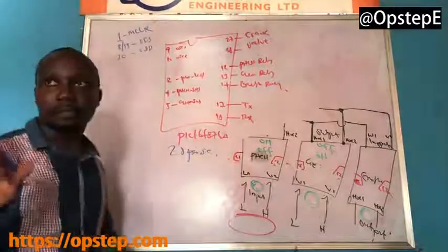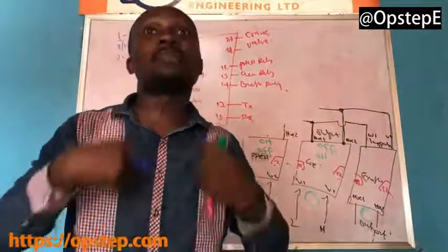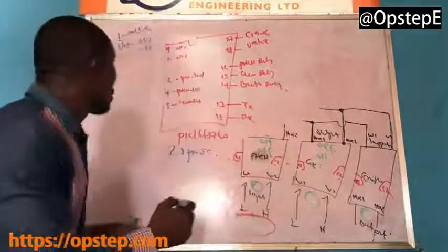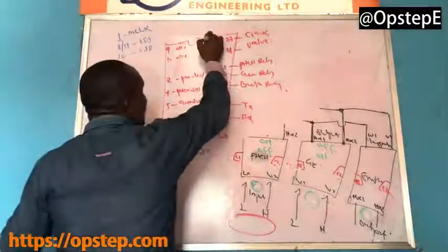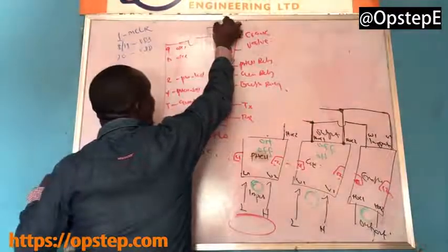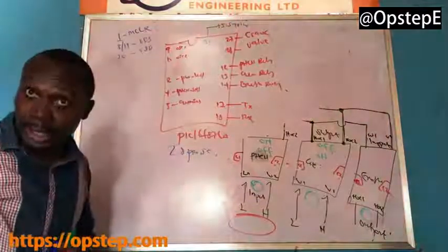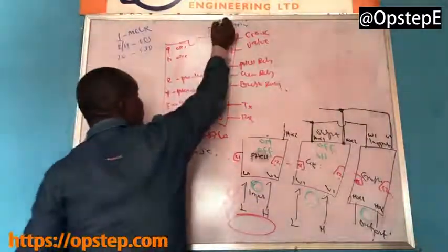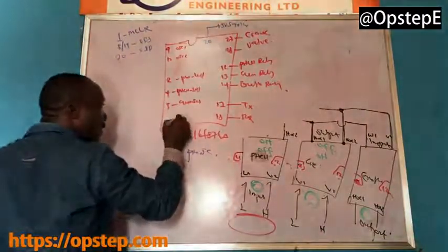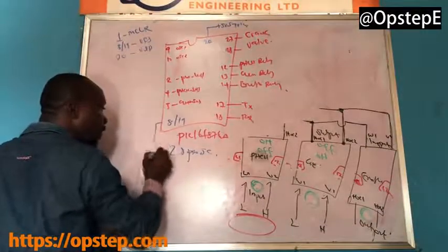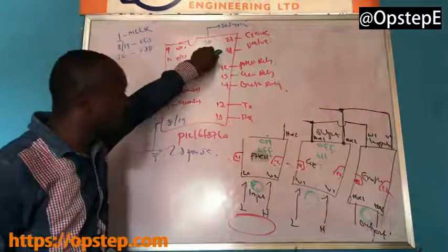And let me explain. Just like any digital IC, the microcontroller requires power to come on. So your pin 20 is where your plus 5 volt supply comes to. Do you understand? Yes. Your pin 20, your 5 volt supply. Your pin 8 and pin 19 are what goes to the negative of the supply. So this is 1, 2, 3. Does it make sense?